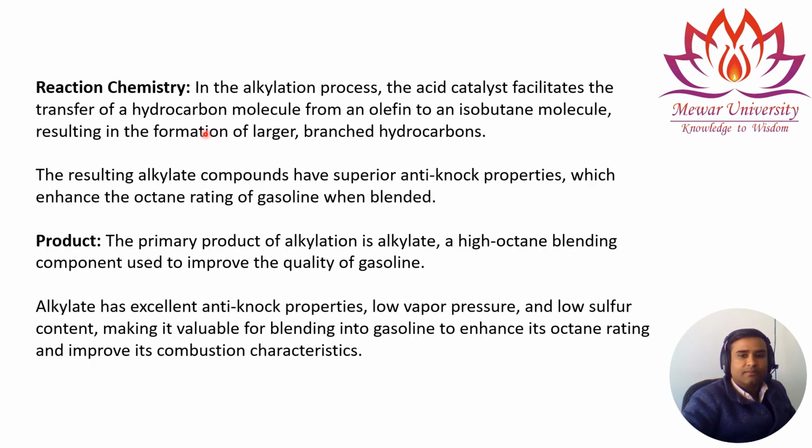Reaction chemistry. Now talking about the chemistry of the reaction, in the alkylation process the acid catalyst facilitates the transfer of a hydrogen molecule from an olefin to an isobutane molecule, resulting in the formation of larger branch hydrocarbons. So the hydrogen molecule joins the structure of two different olefins and they make a larger branch chain hydrocarbon, and the resulting alkylate compound has superior anti-knock property.